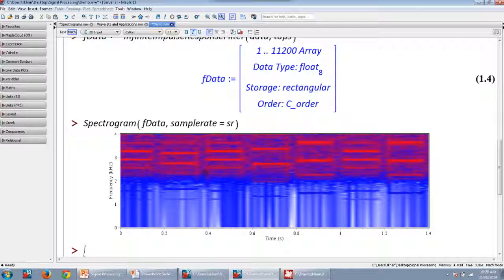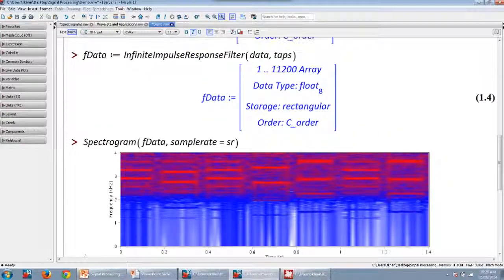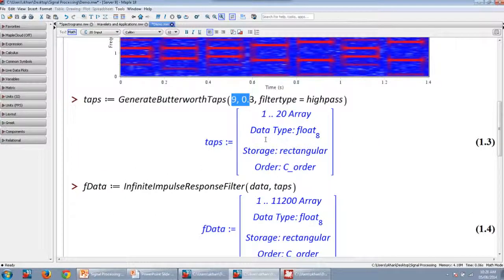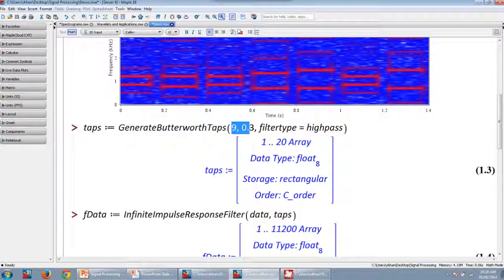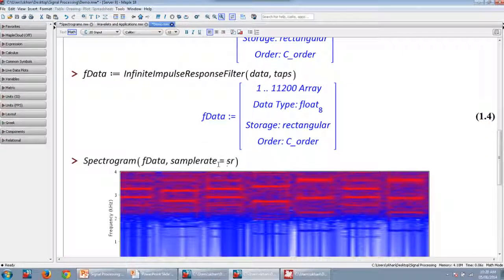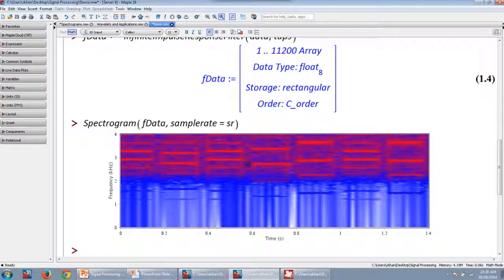And there we go. This is the effect of our high pass filter with these characteristics on our audio file. So you can see that this is clearly different from the pre-filtered audio file. Now if you wanted to, you could write out the updated filtered data into an audio file. What you can also do is fine-tune the appearance or the characteristics of the spectrogram as well.